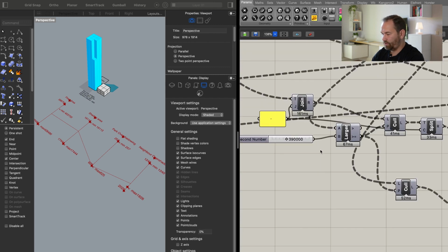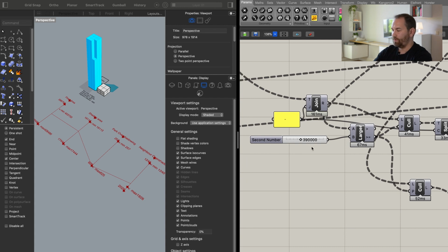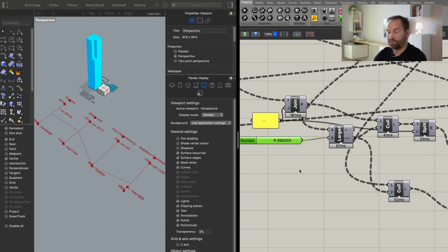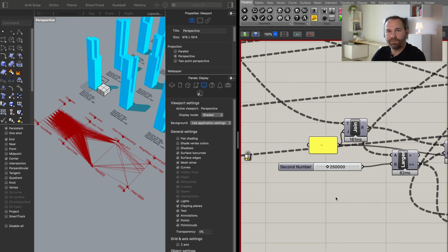And at the moment we are shrinking the choice by filtering based on area down to 45 options out of 6,500. So I'm going to set this to 250,000, and let's see if my computer will be able to calculate all the options that are left. Okay, it finally calculated. It took 5 or 10 minutes, and as you see, we have way more design options now being displayed in our Optioneering interface.